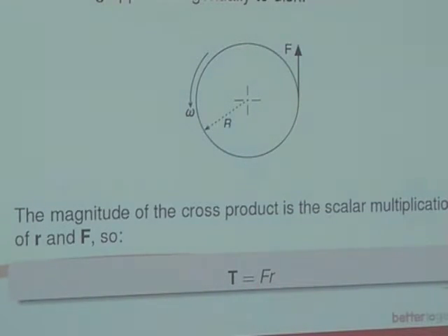Now, as I said in the lecture to do with Racing Academy, during that activity week, the engines produce torque, not power. Well, this is exactly that situation, because in your book you've got a picture. There's a crankshaft, the piston, and there'll be a force being applied by the combustion of the fuel. That applies a force tangential to the crankshaft.